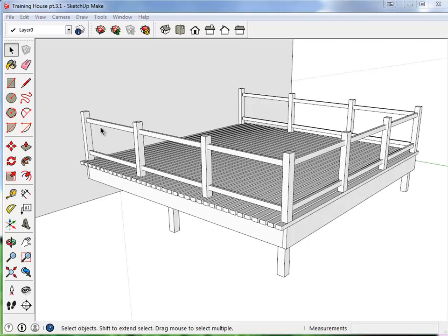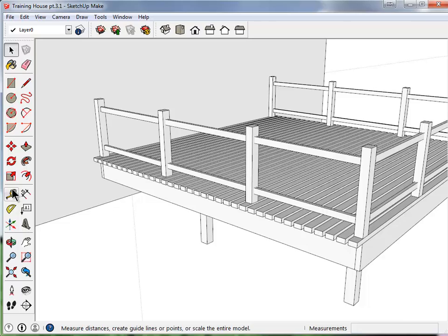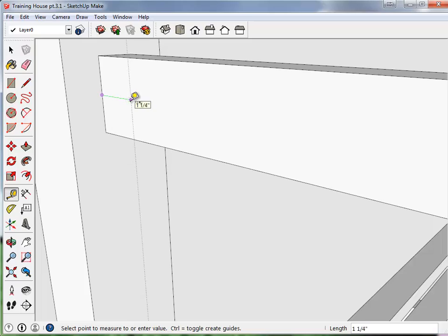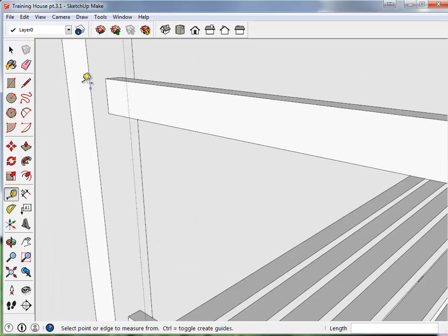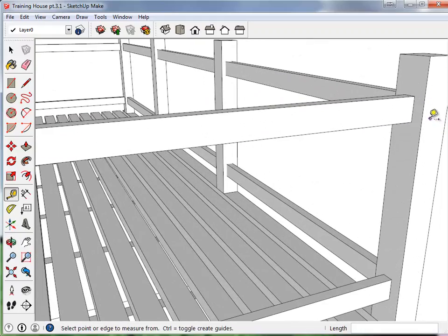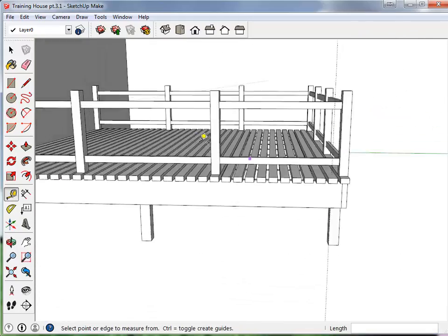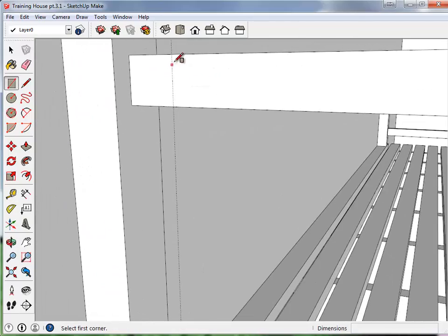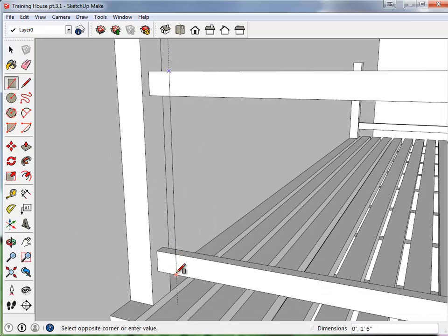Now, with the supports for our railings complete, we're going to put a decorative touch along the side of the railing for slats. Again, our dimension tool will start from the edge and will come in about 2 inches. Let's do the same for this side over here. Now our little slats will consist of a simple rectangle that goes down to the bottom and pulls over.